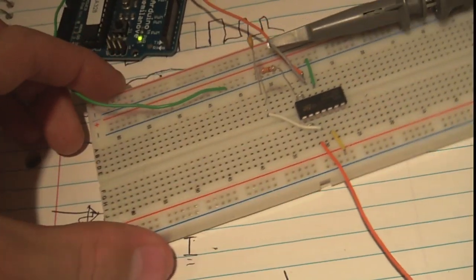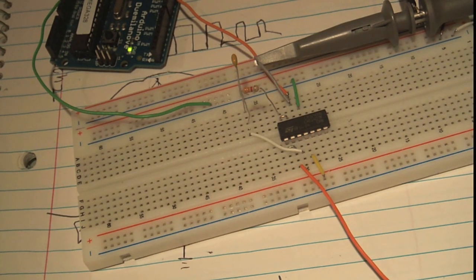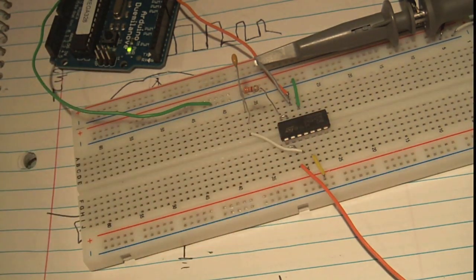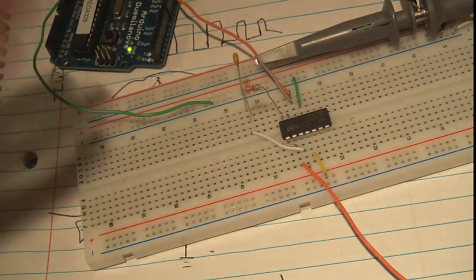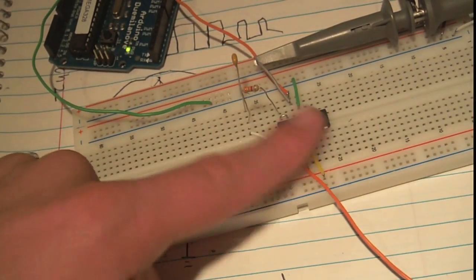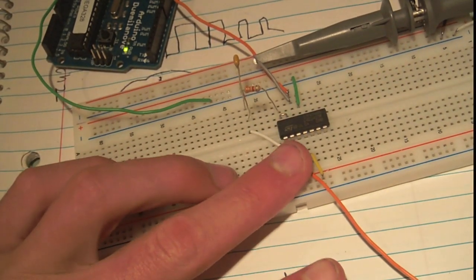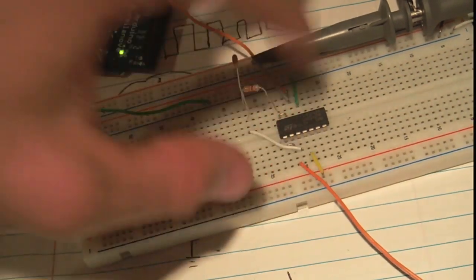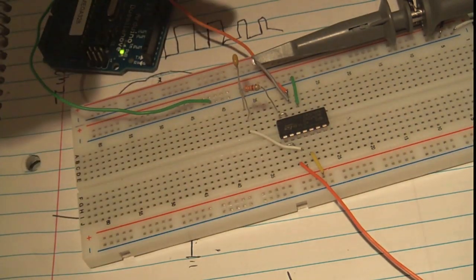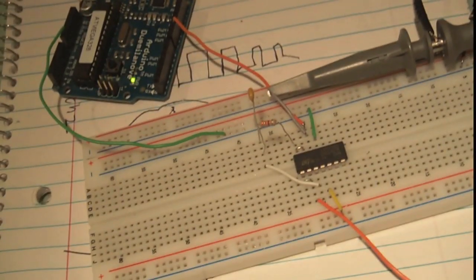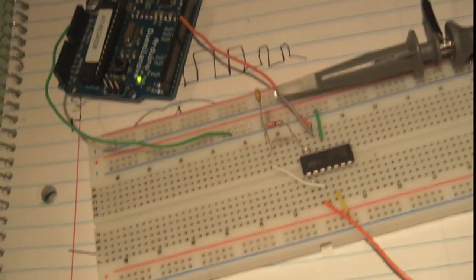I've built it up here on the breadboard, and I'm going to try to explain what I'm seeing here on the scope in a second, but as you can see, I've got the op-amp hooked up here. There's a few things you need to realize. One, this is the LM324, so it has issues with the fact that it can't meet its supply rail. It can't get all the way up to 5 volts, so you can't power it from the Arduino. I have it powered with this separate supply here at 10 volts.